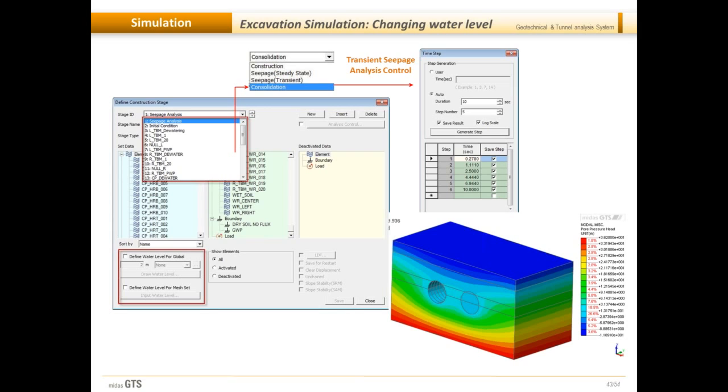So long-term effects are equally important if you are dealing with soil strata that have clay or unconsolidated layers. And for this purpose, while simulating this in your numerical analysis tool, you should alternate the seepage analysis with your construction analysis. So once you see the seepage, then you do the construction, and then you have to alternate the effects. And you must consider the transient seepage analysis as well, where you can vary the seepage flow with time.